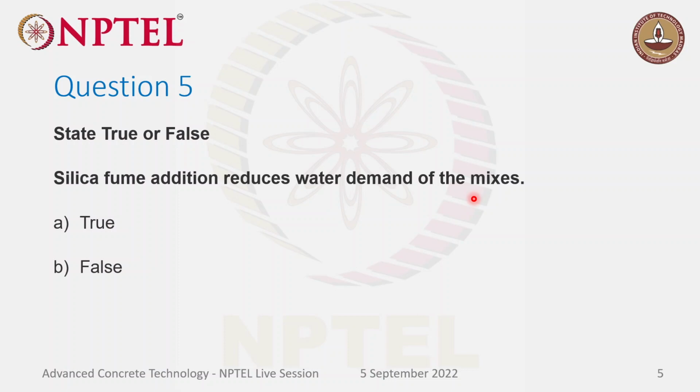And to add, silica fume is a very fine material, and we have to densify it to transport, and then while preparing the concrete we have to mix it for additional time than normal concrete. Okay, let's see your response.